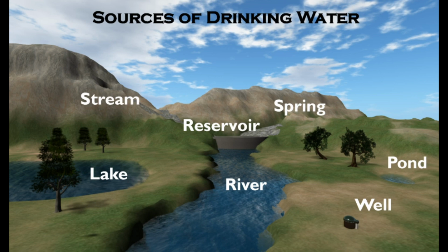Lakes and reservoirs are another great source of water. Typically located in the headwaters of the river system, upland reservoirs are usually sited above any human habitation and may be surrounded by protective zones to restrict the opportunity for contamination. Bacteria and pathogen levels are usually low, but some bacteria, protozoa and algae will be present. Where uplands are forested, humic acid color can be found.